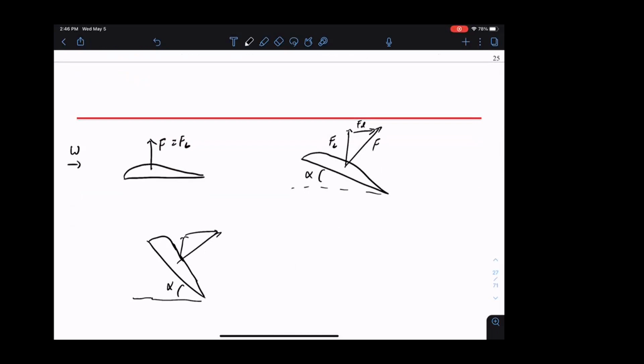And what happens when your angle of attack is too large? Can we operate at a very large angle of attack, let's say close to 90 degrees? The lift force is getting smaller and the drag getting bigger. So that's fine, but then what happens there? You might just break your propeller, or the turbine. Why would you break your propeller or turbine? What breaks it? Is it too much drag force?